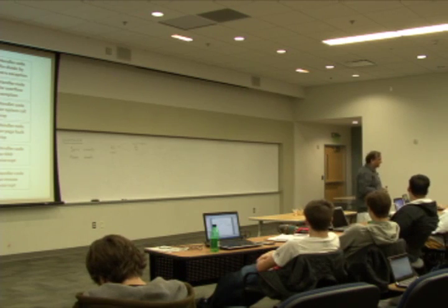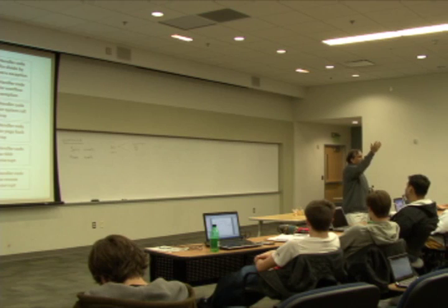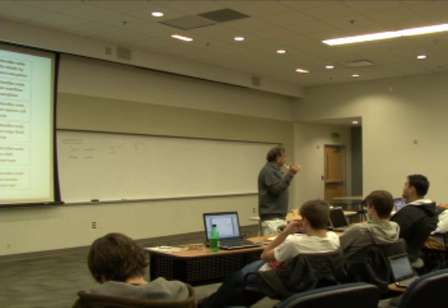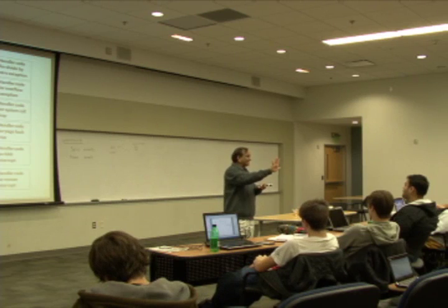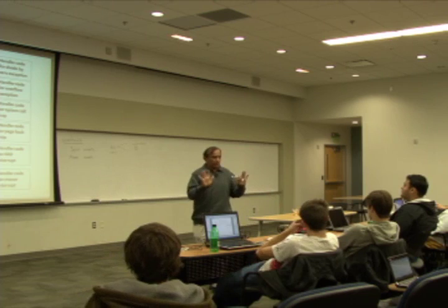Matt. Yeah. Well, what else can be wrong about that, Shane? Yes, an A register. So there are internal registers, right? The data path contains all kinds of internal registers. And now if you say that an interrupt happens in the middle of the micro sequence, then you have state that is inside the data path, and you have to save all that state. That's messy, right? Depending on the complexity of the data path, that's too messy. We don't want to do that.